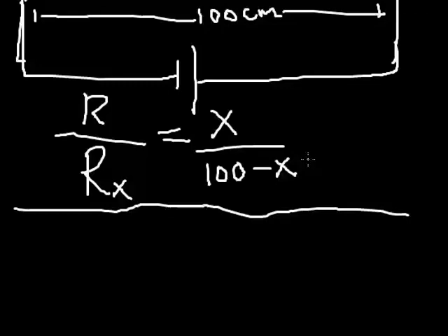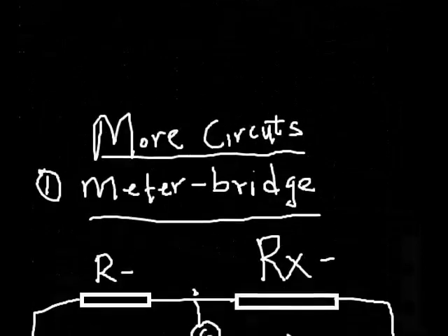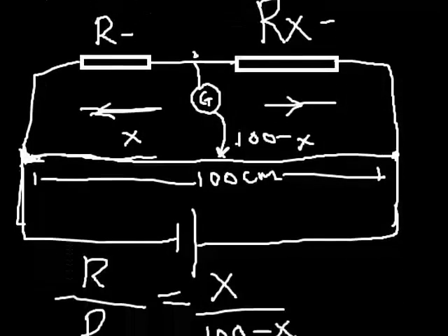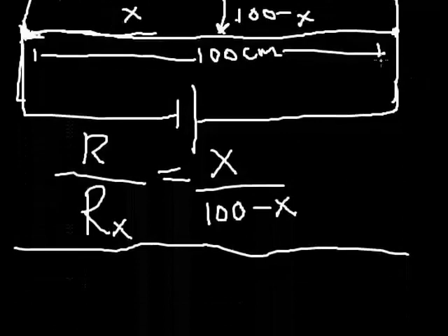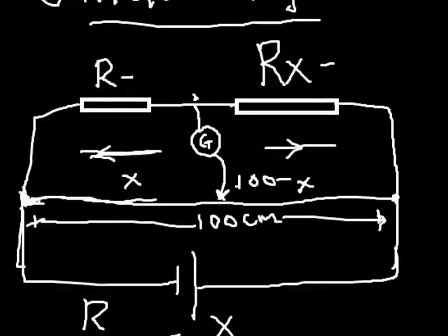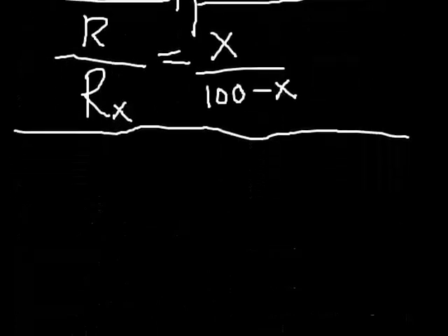So what are Kirchhoff's rules? Kirchhoff actually states two rules. One of the rules is known as the Kirchhoff loop rule, or voltage rule. What does it state? The Kirchhoff loop or voltage rule states that the algebraic sum of voltages around a loop is equal to 0. Now the question is, what is a loop? A loop is simply a closed path that current travels. For example, this is a loop.